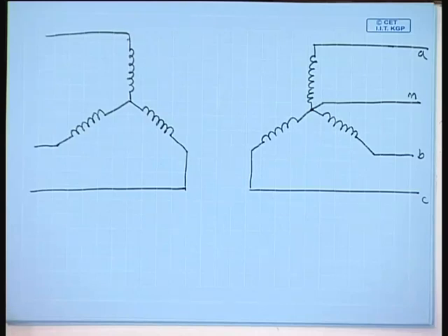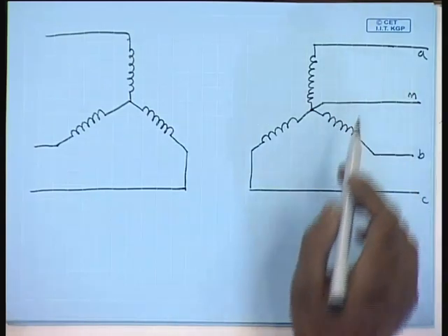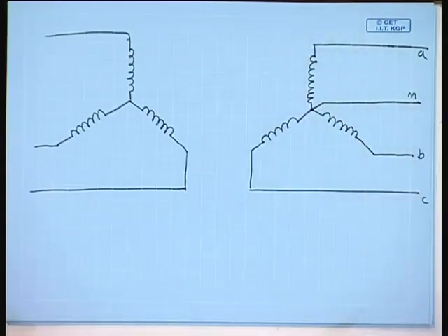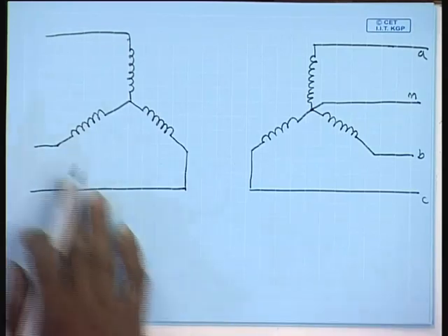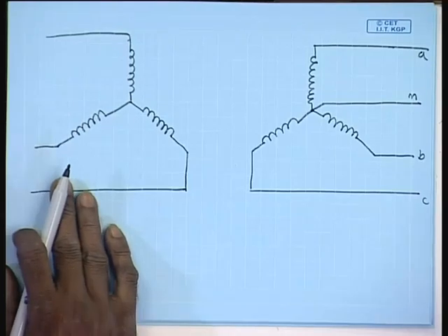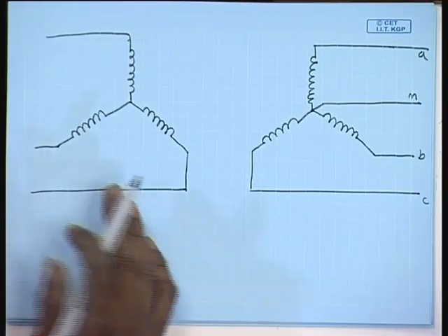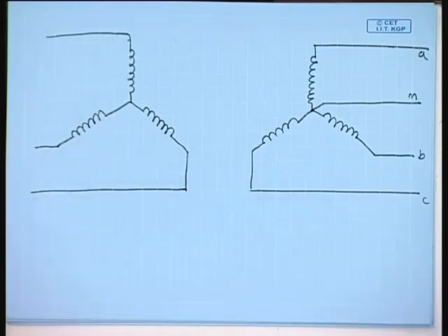that is, the zero sequence current of the low voltage side load current and the third harmonic or triplen harmonic currents, cannot flow. The reflection of that current cannot flow on the high voltage side, which has an isolated neutral. Hence, this produces third harmonic flux distortion. In order to avoid that, some path must be provided for the third harmonic current or reflected third harmonic current, so that the third harmonic flux can be cancelled.